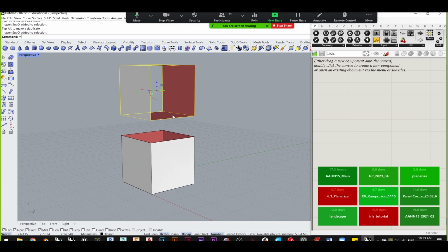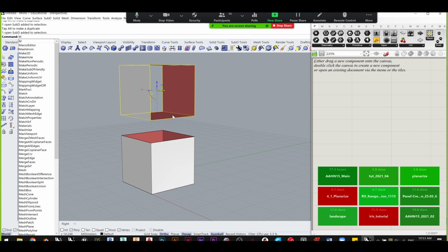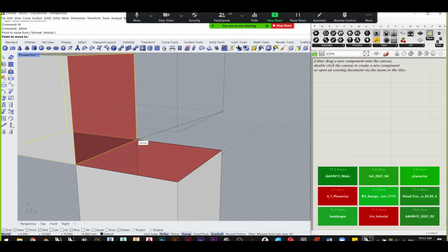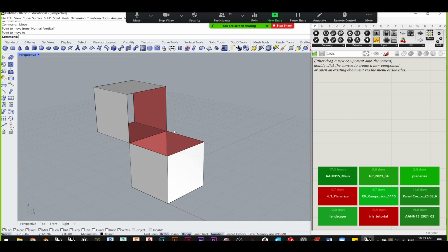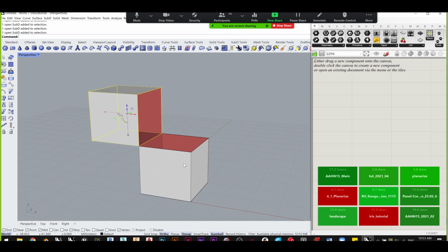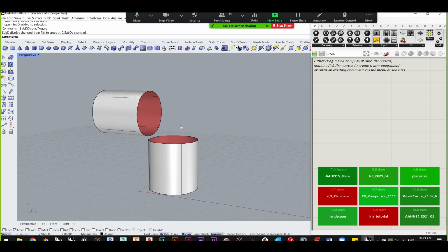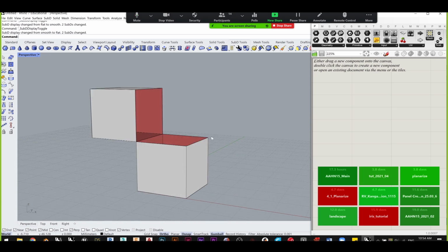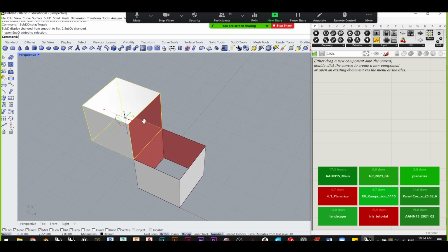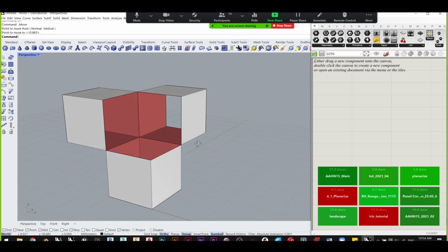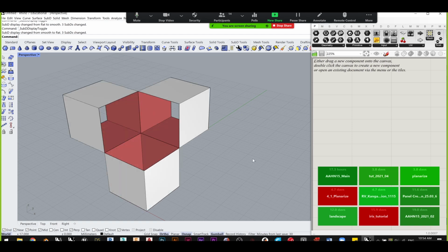And I'll just select it, hit M, short for move, enter, and I'll move it from, let's say, this corner point to this corner point to create this kind of an L shape, right? Or upside down L shape. If I hit tab, you can see that it's basically 2 cylinders. Okay, so we have this done, and now I can just make a copy of that cube, rotate it around the z-axis 90 degrees, and also move it like so. So now we have 3 of them.